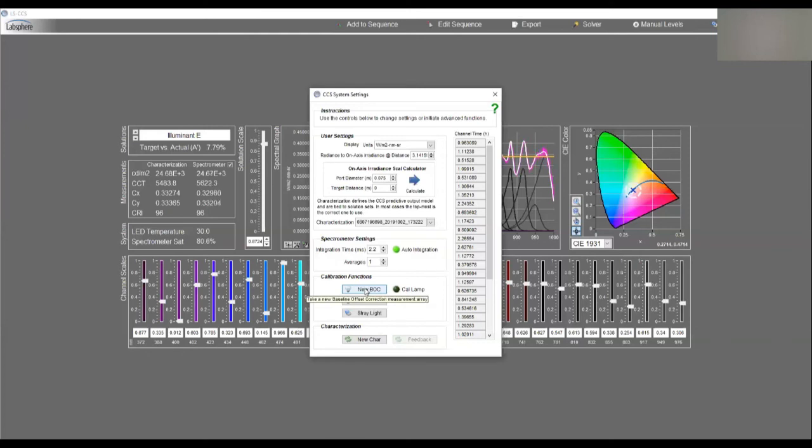When you operate the FT2300 and execute the software, it gives you the option to do a baseline correction. That is simply putting the system in dark, or covering the port and running a baseline offset. It's a dark scan, which then corrects any noise in the spectrometer.